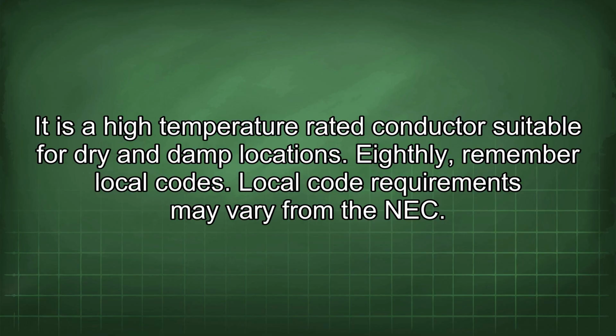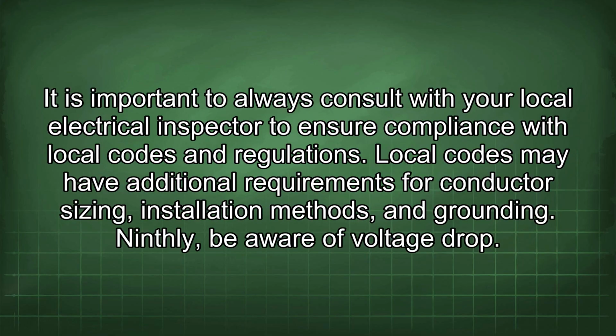Eighthly, remember local codes. Local code requirements may vary from the NEC. It is important to always consult with your local electrical inspector to ensure compliance with local codes and regulations. Local codes may have additional requirements for conductor sizing, installation methods, and grounding.